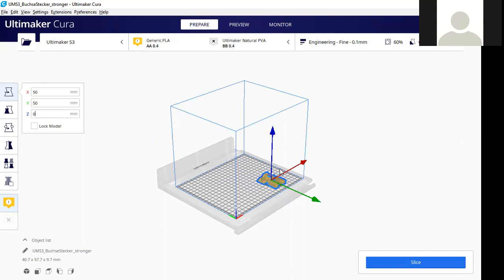You can't have something in the air, isn't it? So let's try a minus. Let me say -5. You can see that it can go a little bit into the print bed, meaning that during my printing, just half of what I have here is going to print. Okay, that is for our first item, which is move.